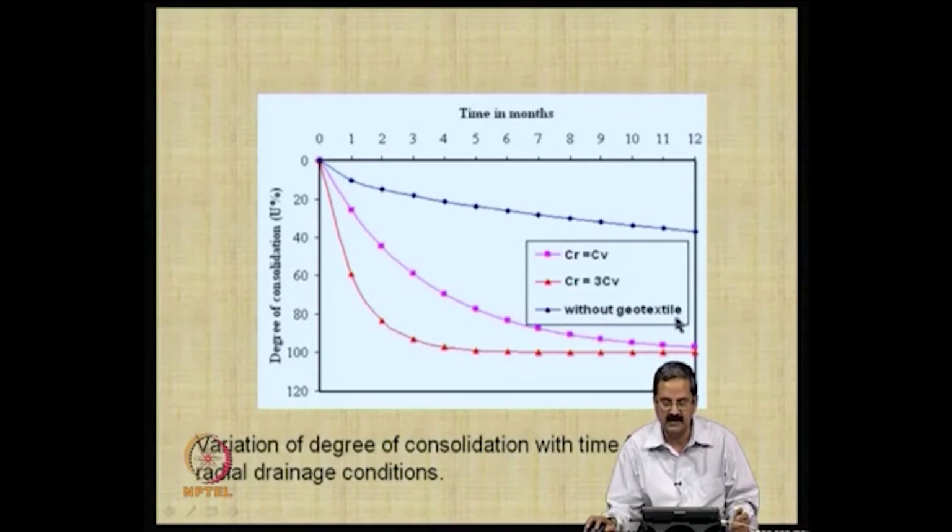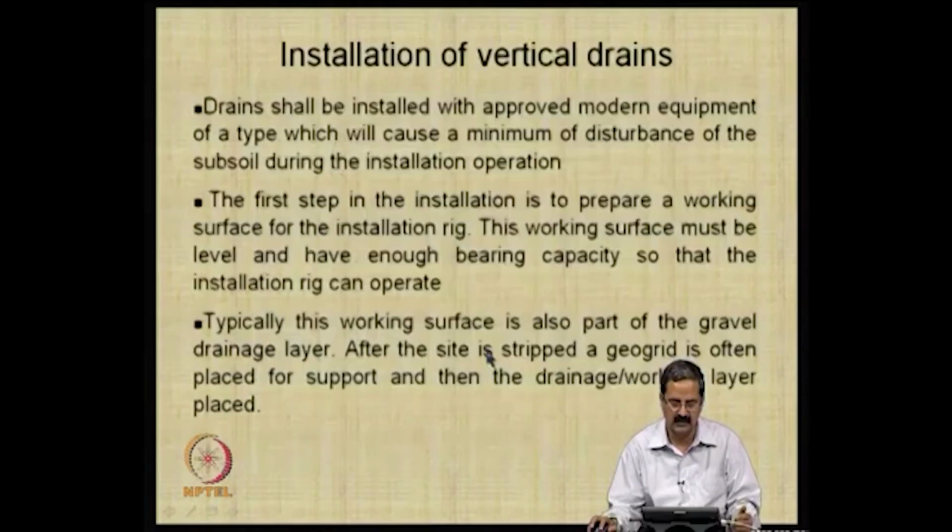But whereas, as I just mentioned, the vertical consolidation will be slightly smaller. So, you put that, I mean radial, and so you see radial consolidation is higher than the vertical consolidation, normally 2 to 3 times one can measure in the field. So, you can see that 100% is achieved within maybe 4-5 months, which is a very nice result actually, with some of the actual coir properties. They are applicable to both materials. It is a very interesting observation that yes, some of these materials could be used and you can get what you want. This is an important observation.